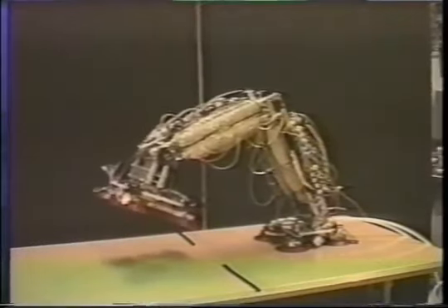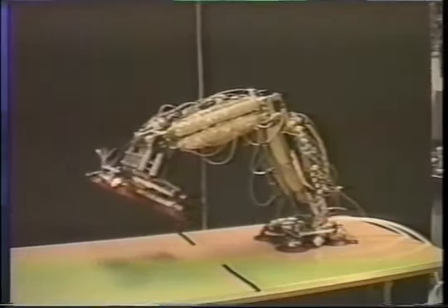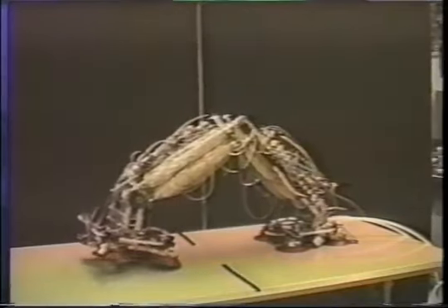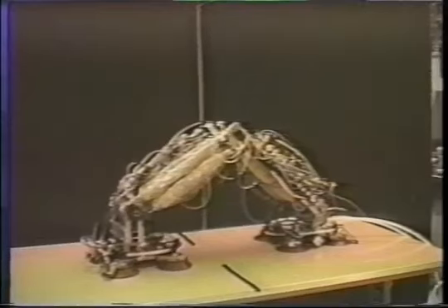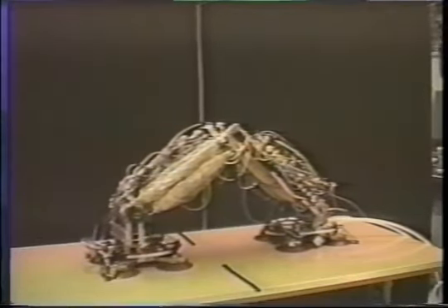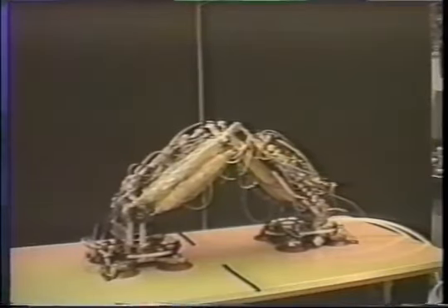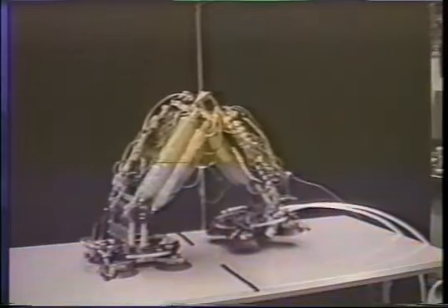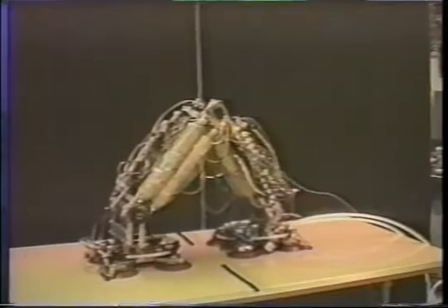Power is carried to the robot via a tether that also carries a serial communication link to the host computer. Walking is achieved by a sequence of extend and contract behaviors that move the robot along, much like an inchworm. Foot-orienting behaviors and vacuum control are triggered by optical proximity sensors on the robot's feet.